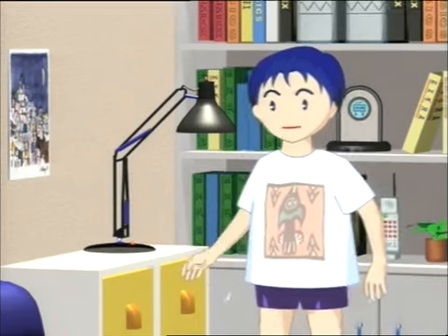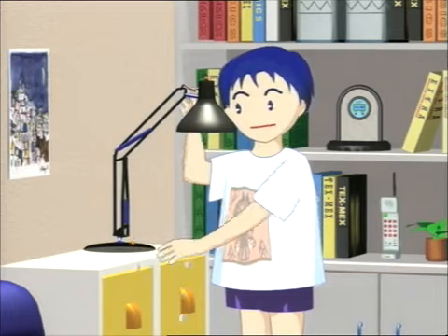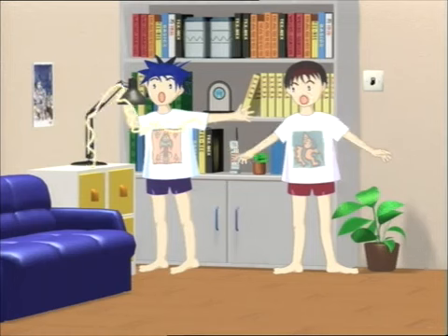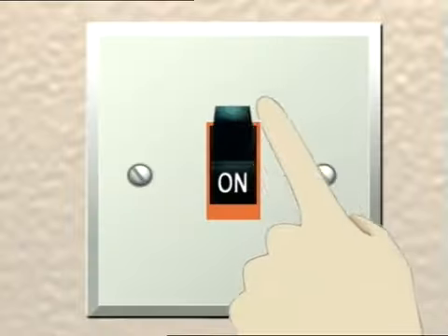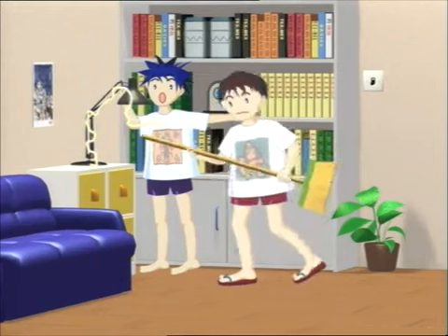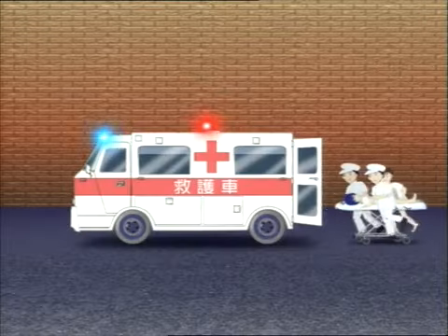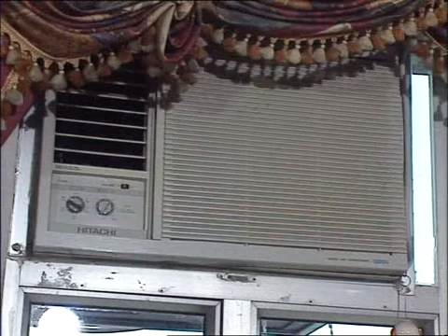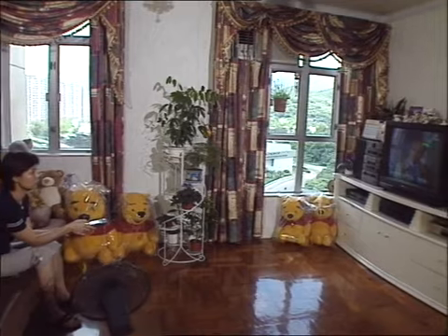Never attempt to touch an electrical appliance with wet hands. When you see someone caught by an electric shock, don't try to push him away with your hands, because this will make you a victim of electric shock as well. You should cut the power supply off immediately or use a wooden stick to separate the victim from the mains. Then send the victim to the hospital immediately for treatment. In short, we can avoid accidents if we handle electrical appliances with care.